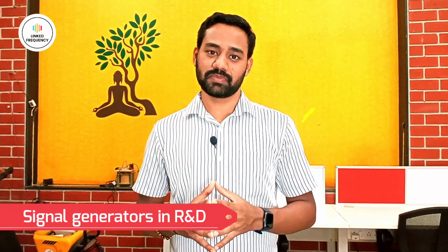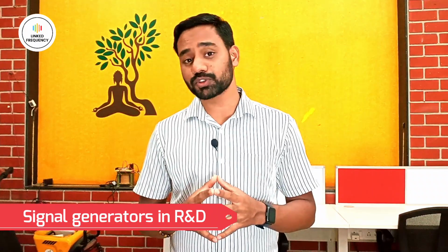Fourth one is signal generators in logic systems. When you go to a laboratory or most small scale applications where you need a specific signal, like a square wave with a specific frequency, then you can use a 555 timer IC as an oscillator. Of course, we have crystal oscillators and very precise RC oscillators, but in most small scale applications where there is no possibility of a high cost investment, or the product is very low end, the 555 timer IC is widely used.